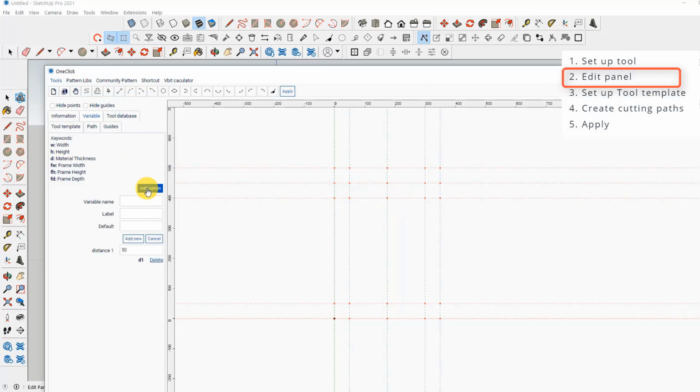Another variable, D2, label distance 2, and default value 40 milli. And do similarly, D2, or maybe this is 30. So in the box value, we can type in a new value and then hit enter. Then it's gonna be adjusted. And from the other side, W subtract D2.